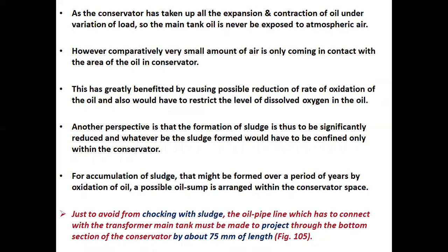Another perspective is that the formation of sludge is significantly reduced, and whatever sludge is formed would be confined only within the conservator, for accumulation of sludge that might be formed over a period of years by oxidation of oil.